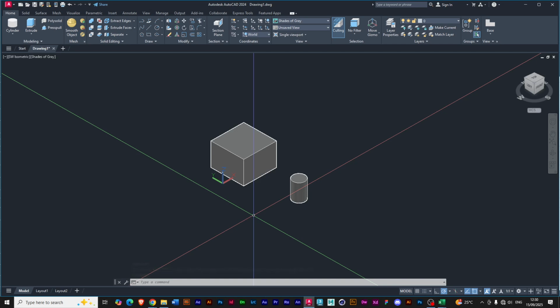The z-axis is supposed to be pointing towards you, the x-axis pointing horizontally, and the y-axis pointing upwards. But in these softwares, the z-axis is pointing upwards, the y-axis is pointing towards you or away from you, and the x-axis is pointing sideways. So it's not an error in the setup. It's based on the world coordinates.